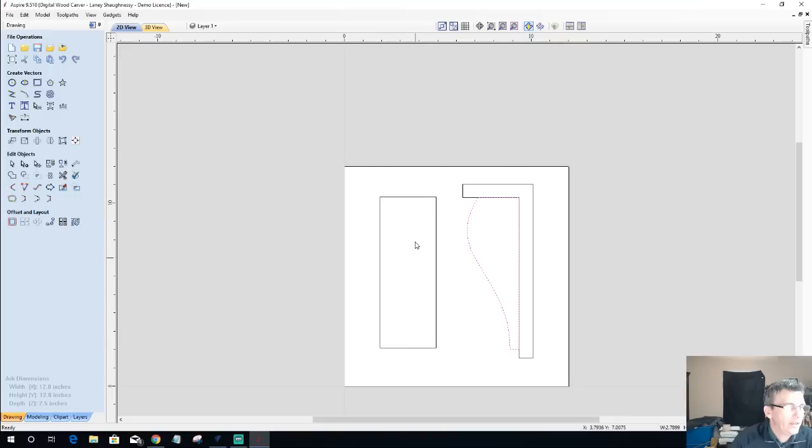What we need to do is create this curved profile that's going to get cut out of the front of my part here. It doesn't matter which way I'm carving it, whether I'm carving it horizontally like this on my board, or if I rotated it back 90 degrees, either way, it's still going to work. For this curve to sweep along this profile, all I need is my top and bottom line.